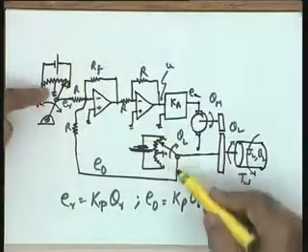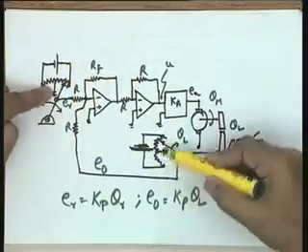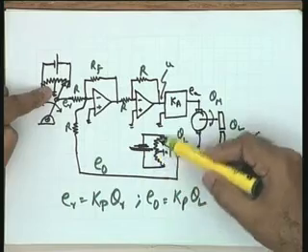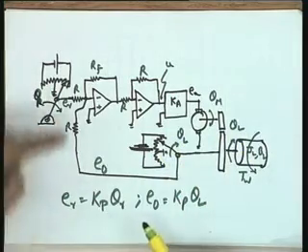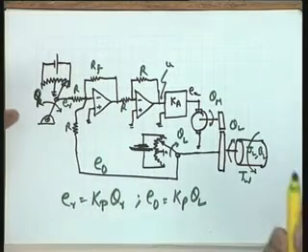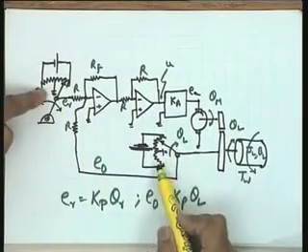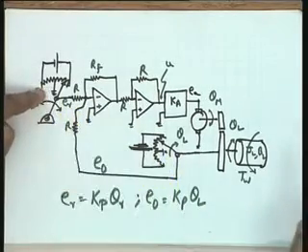The sign I have inverted, minus plus and minus plus taken this way. You will please note the wiper on the potentiometers have been taken in this way, that at this particular point the input of the op amp is ER minus E naught, where E naught is the output voltage of the potentiometer. This you can see with respect to this potentiometer wiper R movement.